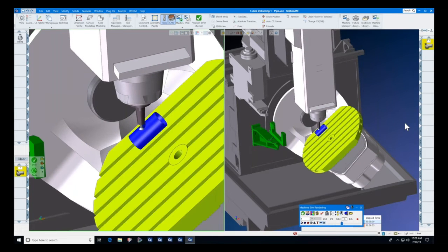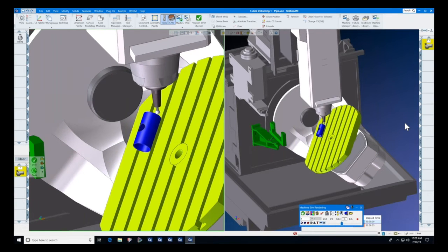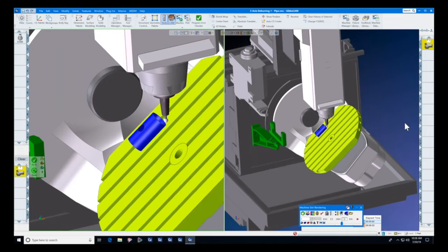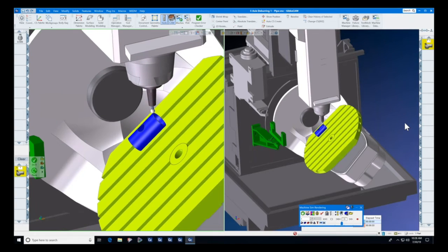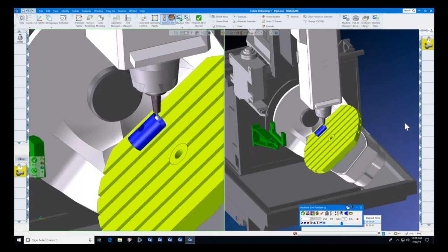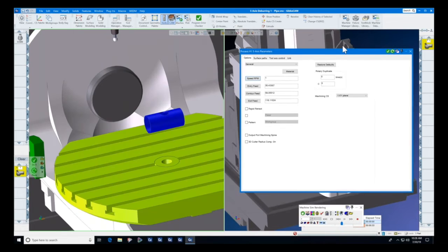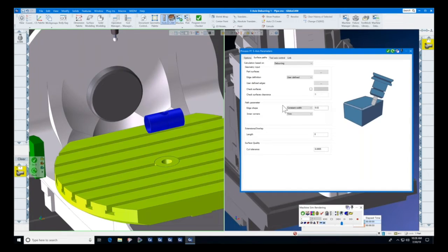And again, this works on very, very complex 5-axis surfaces. And for the most part, it's automatic. We simply click the surfaces, we click the edges, or not click the edges. We just had the edges visible. It found the edges automatically. And by the way, while it is doing its deburring, let's open this and let's look at here. We have tool parameter, edge shape, constant width. We click here, and as you can see, the graphic says this is what we want for a deburr. Well, we can go all the way down to thousandths or a half a thousandth or five ten-thousandths.